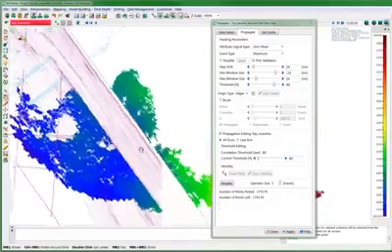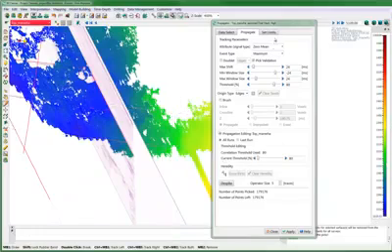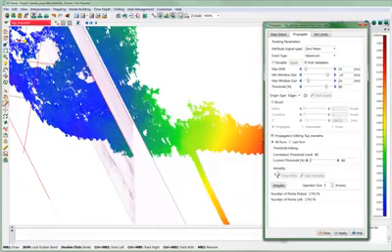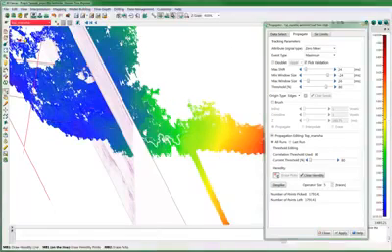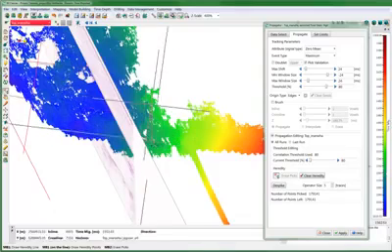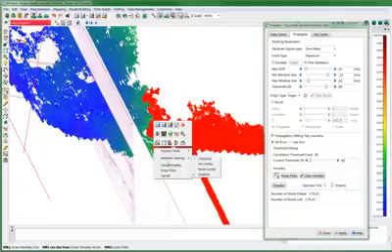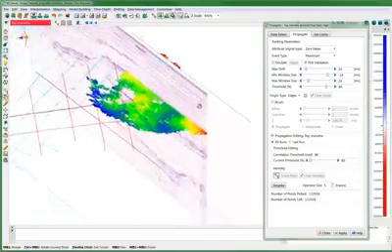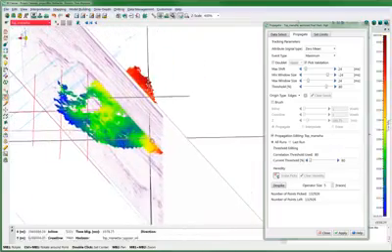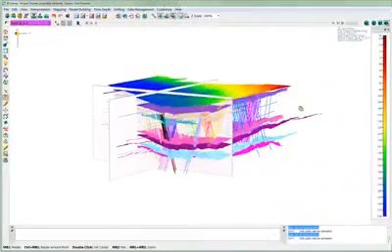We can QC the horizon by displaying many kinds of attributes, such as, for example, the z-value of each point of the horizon. We can also QC the result using the heredity factor. By clicking on one point on the horizon, we will be able to view the path that has been followed to generate this point. By clicking on one point of the line, we will be able to erase all the descendants of this point on the horizon. It will allow us to control the picking, taking into account the correlation coefficient used by the propagator.